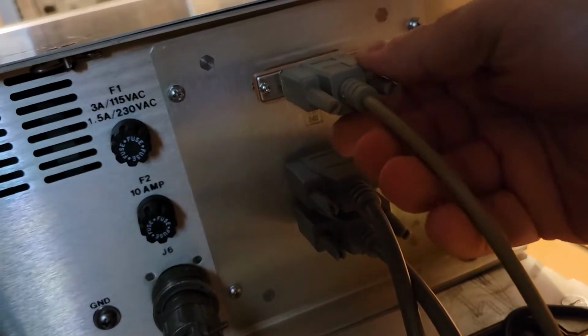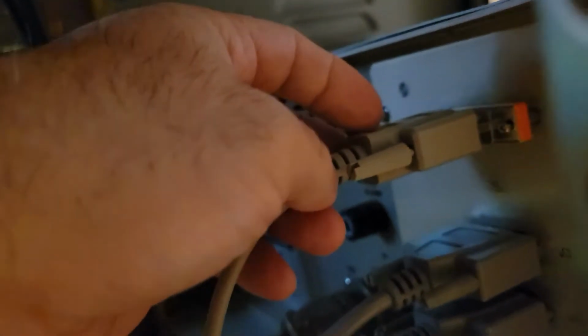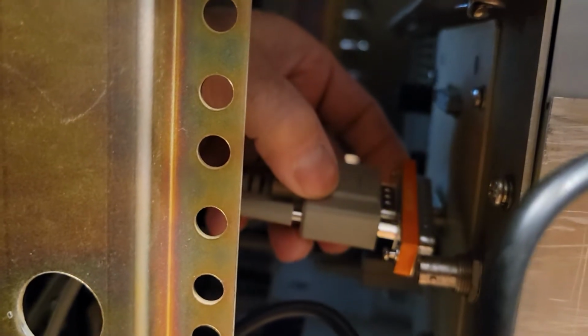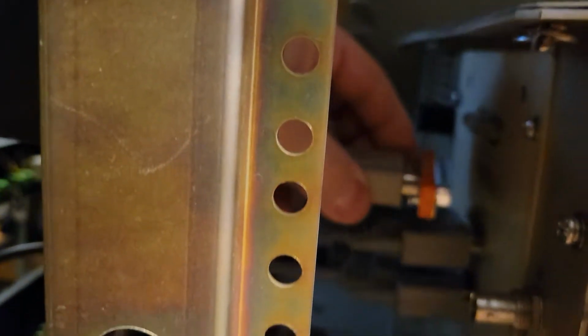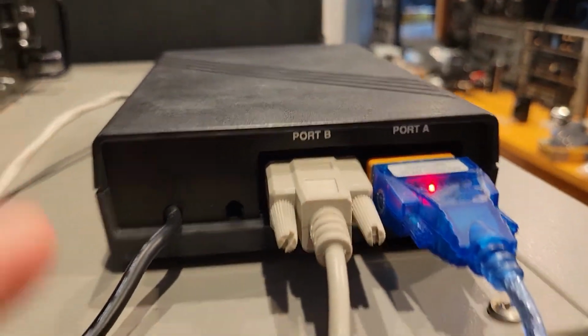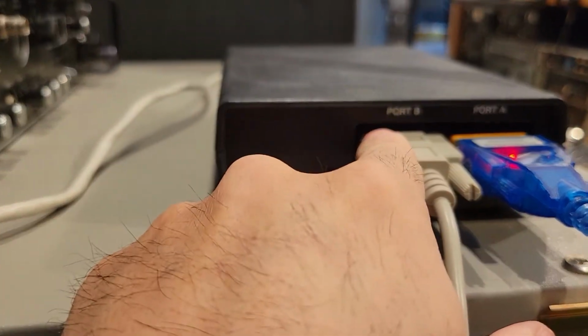And then we have RS-232 coming out of this jack, and I'll just point out, see if I can get a good shot of it. I had to use a 25 pin to 9 pin adapter. So here's 25 pins. But on the other side, I happen to have this 9 pin cable. So I used just a straight adapter, and not even a gender change. Okay, that then goes into, here's the communications adapter, goes into port B.